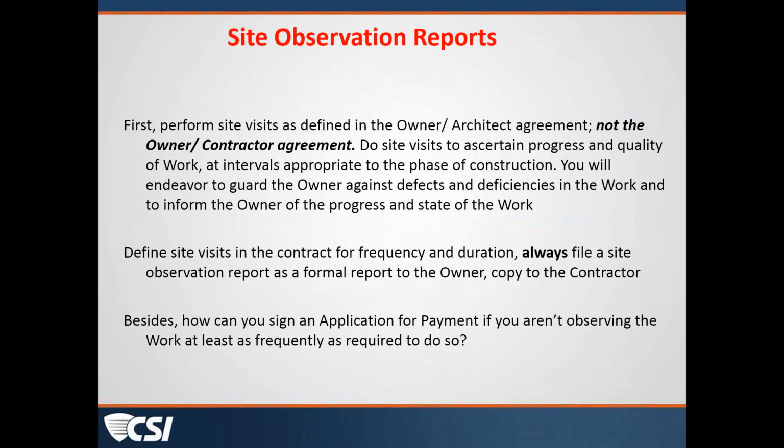In some locations in the documents, the proper window was detailed, but in the specifications where the model number of the window was included, there was only one model number type, and there should have been at least two, probably three, in this project. And on some of the drawings, I'm sure nobody on this call would ever do this, but there were some cut and paste window details included in these documents, and some of those were right, and some were not. And so the questions immediately began: well, who should have caught this and when, and why weren't more questions asked during construction?